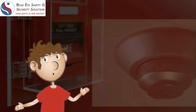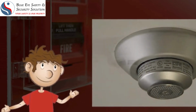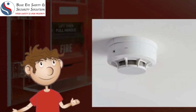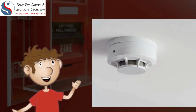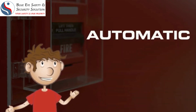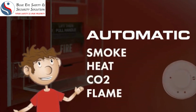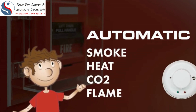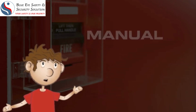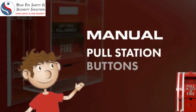Next are the initiating devices. These devices transmit a signal to the fire alarm control panel indicating that there is a possible fire. There are two types. Automatic devices are typically detectors that can measure or identify the presence of smoke, heat, carbon monoxide, and flame. Examples include a smoke or carbon monoxide detector. Manual devices require a person to activate them. These include items such as pull stations or alarm buttons.